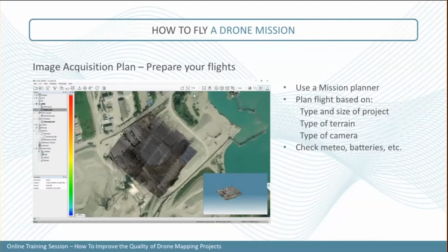Other elements that are quite important: the type of terrain you're targeting. So take into account if you have some variation of elevation in your project, so you'll make sure that you have a constant ground sample distance for your project.